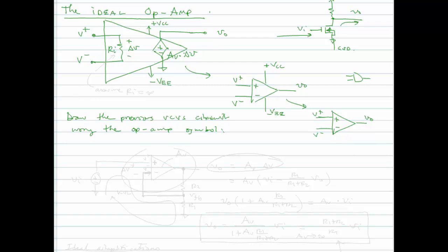So what we will have is our operational amplifier. We have VO, and we have our input signal VI, and it will go into this positive input. We have our voltage divider coming off of our output, R1, R2. This junction between here is V feedback, and we're going to take that and connect it back to our op-amp.